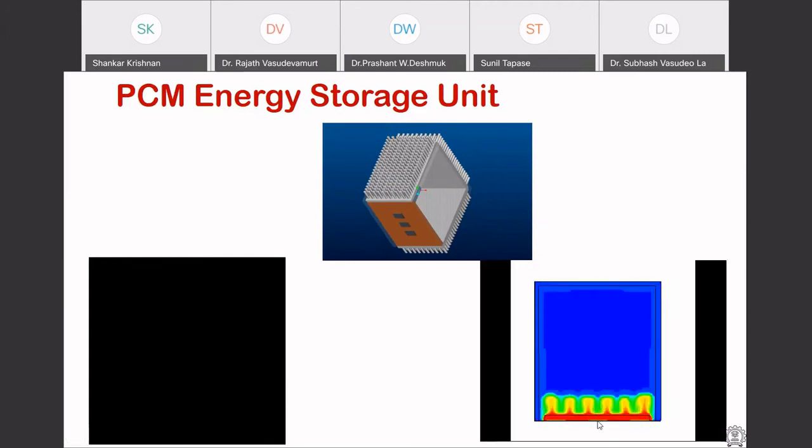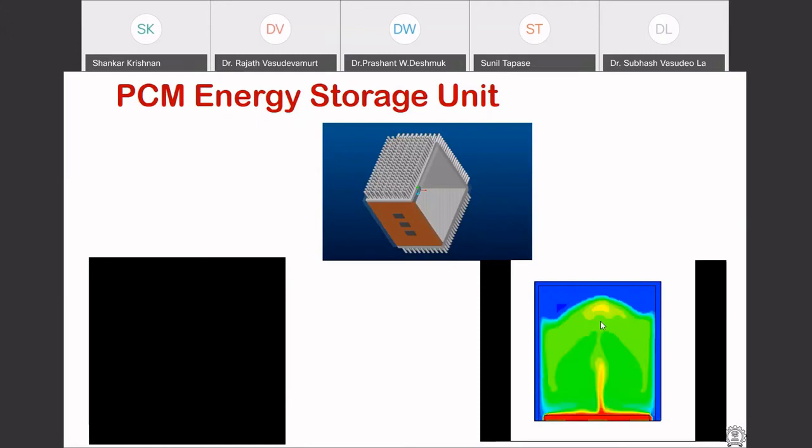So you can put these heat sources on the bottom as well, and then you start to see some very interesting natural convection features. These are called Rayleigh-Bénard convection cells that arise where there is an instability, and beyond a certain melted range, you start to see that initially there are 5 or 6 unit cells, they start to collapse into one, and finally it becomes turbulent flow. Here this modeling work was done assuming laminar flow. However, we know that once it becomes a single plume, it was actually turbulent. So we have shown turbulent flows as well.